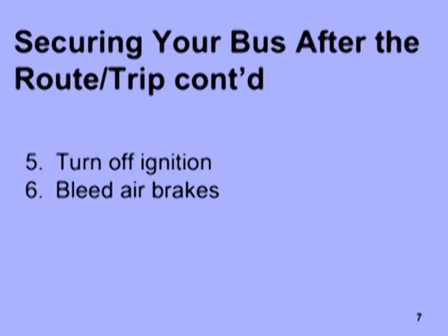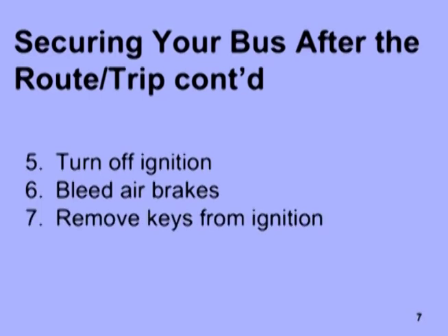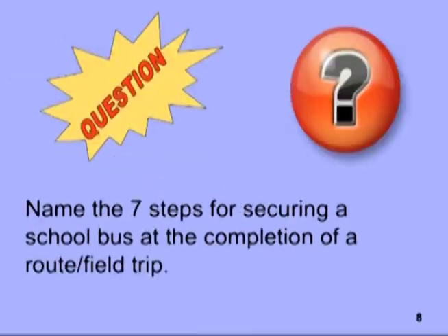Bleed the air brakes to 20 psi to ensure that the parking brake is set and cannot be released without the engine running. If the parking brake does not engage and hold the bus, contact fleet maintenance immediately. And then remove the keys from the ignition and store them in the appropriate location according to your transportation department guidelines. Now let's see what we have learned.